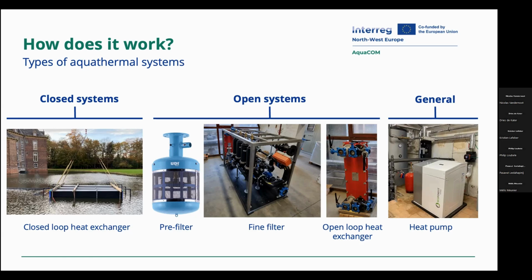Because we do the heat exchanging in the heat exchanger itself, and the heat exchanger is a narrow plate heat exchanger. So we have very thin plates close to each other at a distance of smaller than 0.5 millimeter. To avoid that we create obstructions in that heat exchanger, that's why we need to do the filtration in front of it.